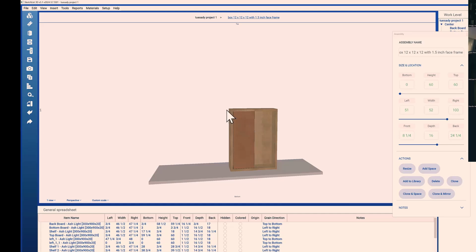If I wanted to wrap a molding around the top through 3 edges, the hard way is to create the board with a 45 here, clone and mirror it over there, then put another board on the front with a 45 on both ends, and then contour the fronts.